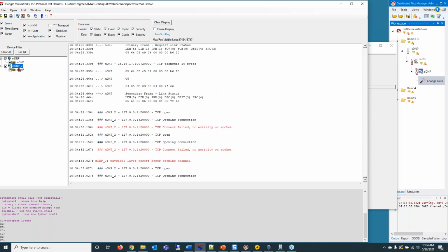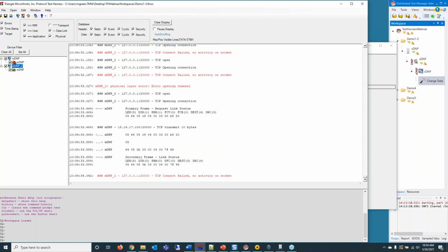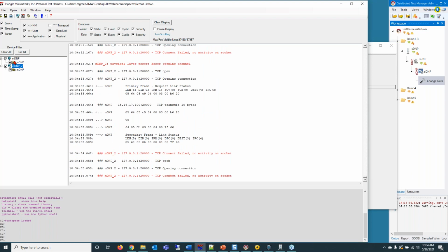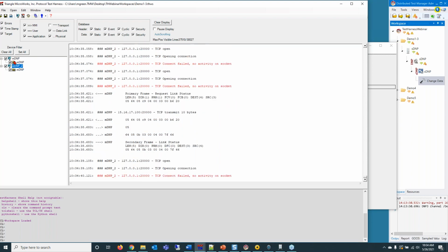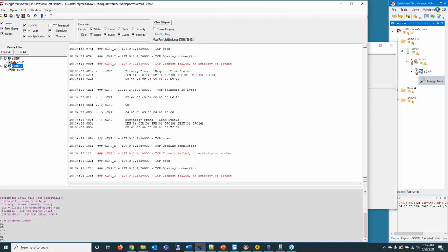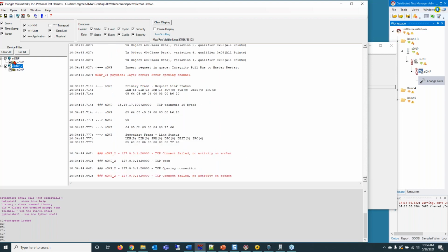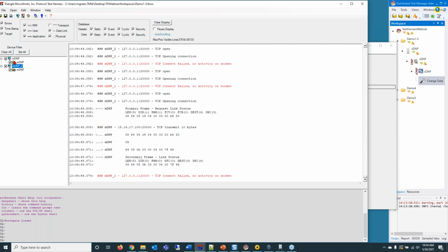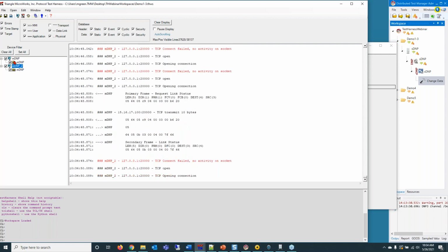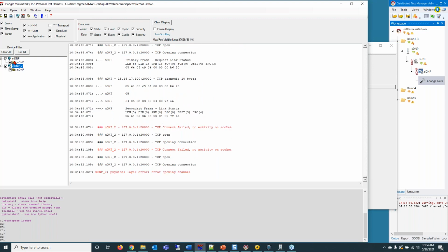There's another way that you could do it, and that is by adding an extra session to an already previously created channel, which is the TCP/IP connection. One reason you might want to do this is if you have one TCP/IP connection to a remote terminal server, which then will split that up into multiple serial connections to different outstations.